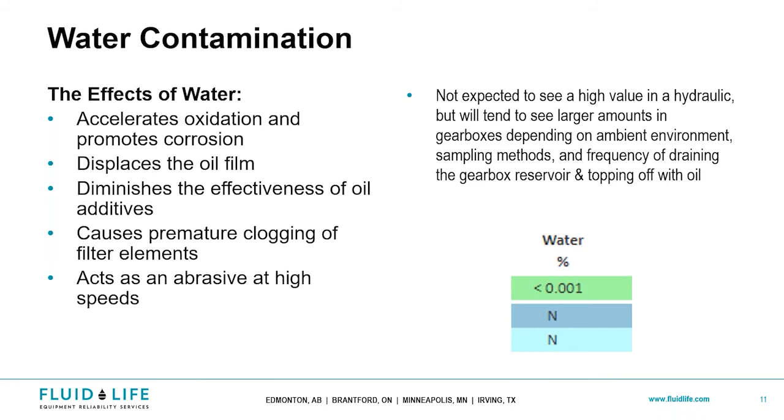It's going to displace your oil film, so all the lubrication properties, because water and oil generally don't mix and have different chemical properties, different density properties. That could actually push your lubrication away from all those moving parts that need something in between them to not chip off.